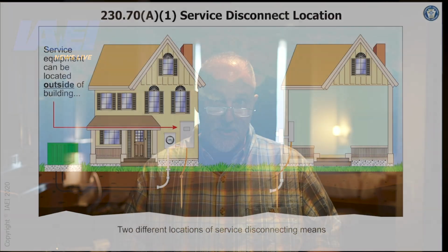A vault, not typical for dwelling units. Conduit under not less than 18 inches of earth beneath the building, and then rigid metal conduit or intermediate metal conduit routed directly through an eave, not a wall. Okay, take a look at 230.6 again for that information.